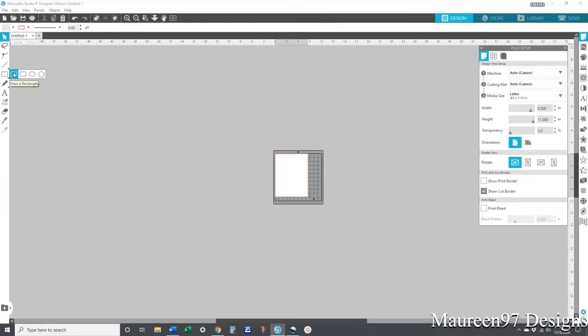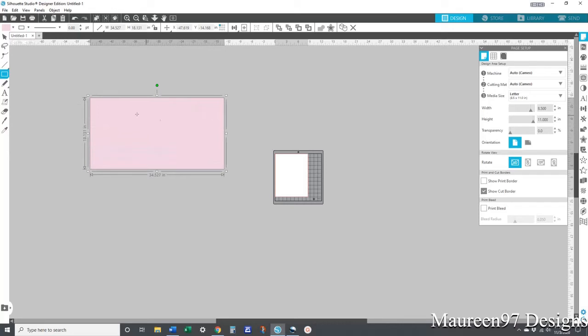So I'm just going to start by drawing a simple rectangle, so I'm going to pick that. And then up here in this top middle section, you can actually pick a fill color, and I'm going to pick just this light purple down here. And then this is the outline color, and I'm going to pick black just so it's a little bit easier to see. And all you do is click and drag, and you've got that light purple box with the black outline in whatever size you made it.